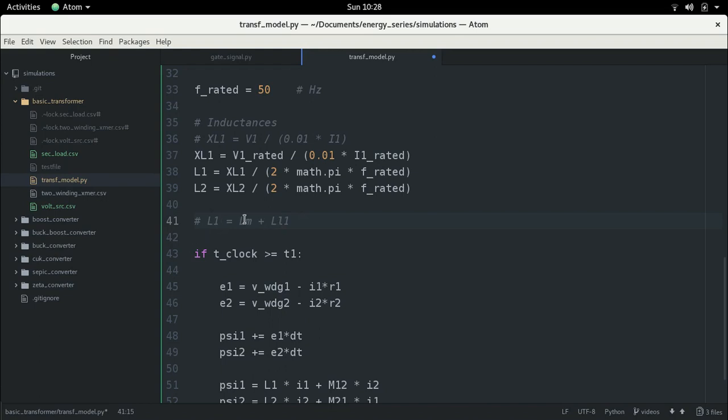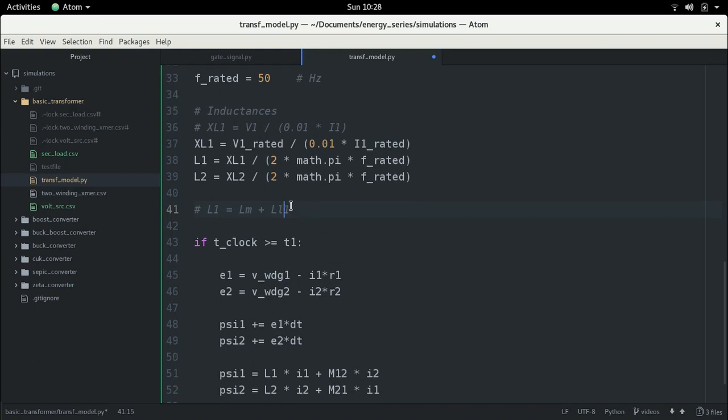So now the question is, how do we determine this? We determine this by a simple rule, that is, we just say how much is usually the leakage that we would like a transformer to have. Now this can be determined using experiments such as the open circuit test and the short circuit test. You can determine these things, or you can take a simple value, like the usual 1% value.